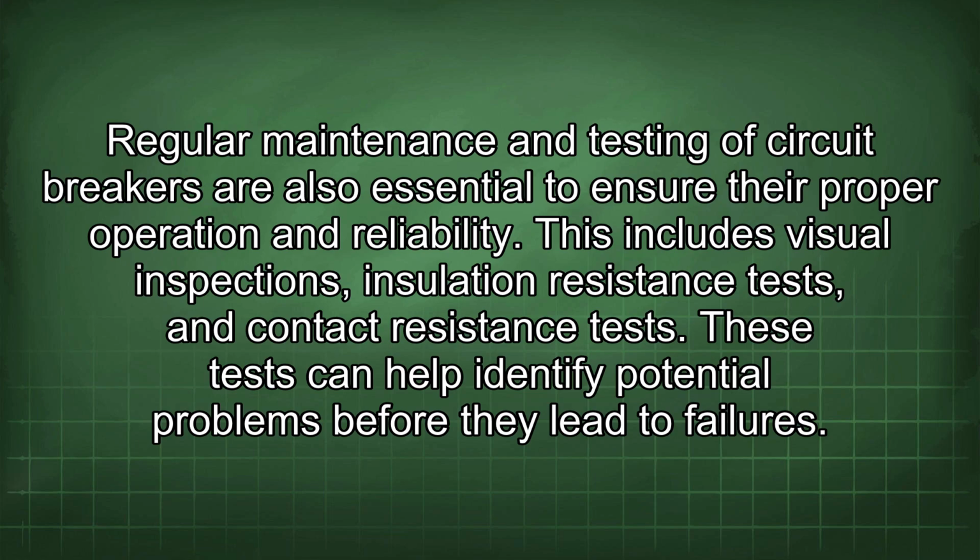Regular maintenance and testing of circuit breakers are also essential to ensure their proper operation and reliability. This includes visual inspections, insulation resistance tests, and contact resistance tests. These tests can help identify potential problems before they lead to failures.